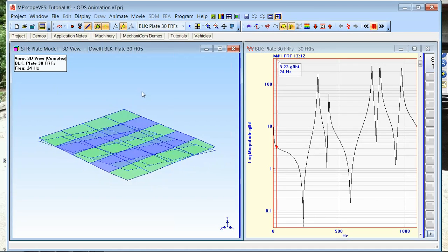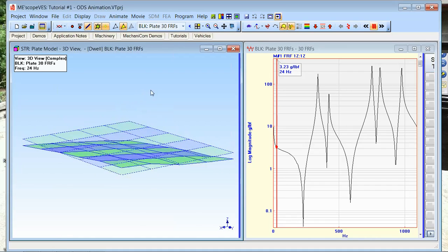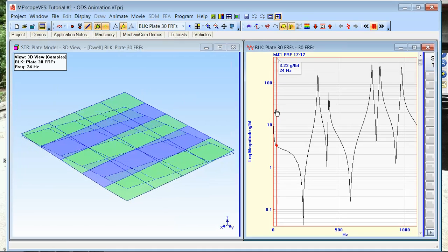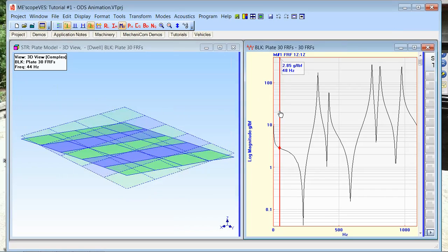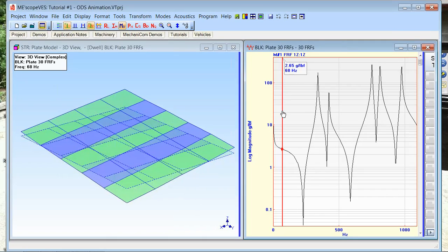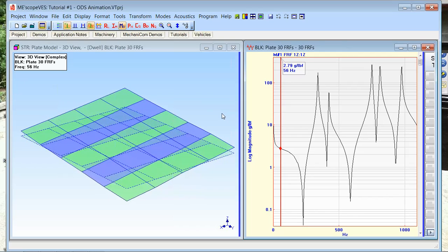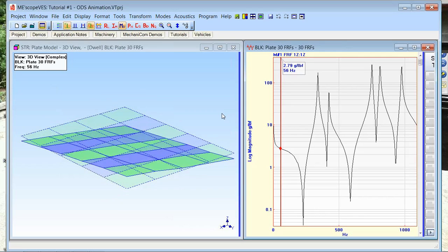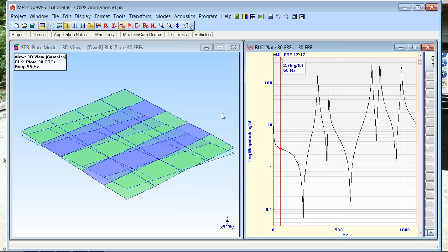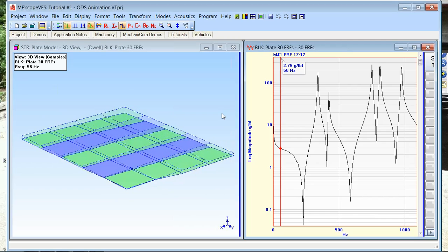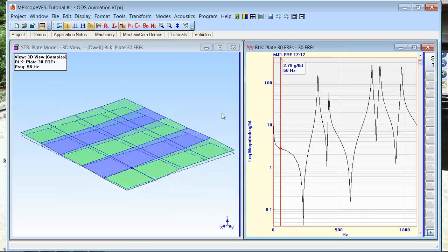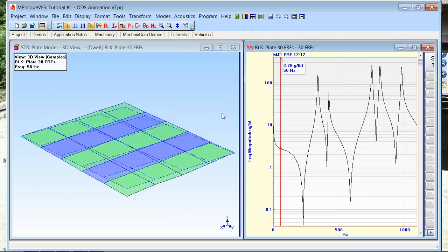Now, if I took some bad measurements, or if I had some sign reversal, or had maybe impacted from the bottom of the structure, then that point would be moving out of phase, or wildly differently than the other points. So that's the first thing I want to do with the data: make sure that I've got a good data set here. Now we're going to go out and put the data close to one of these peaks.